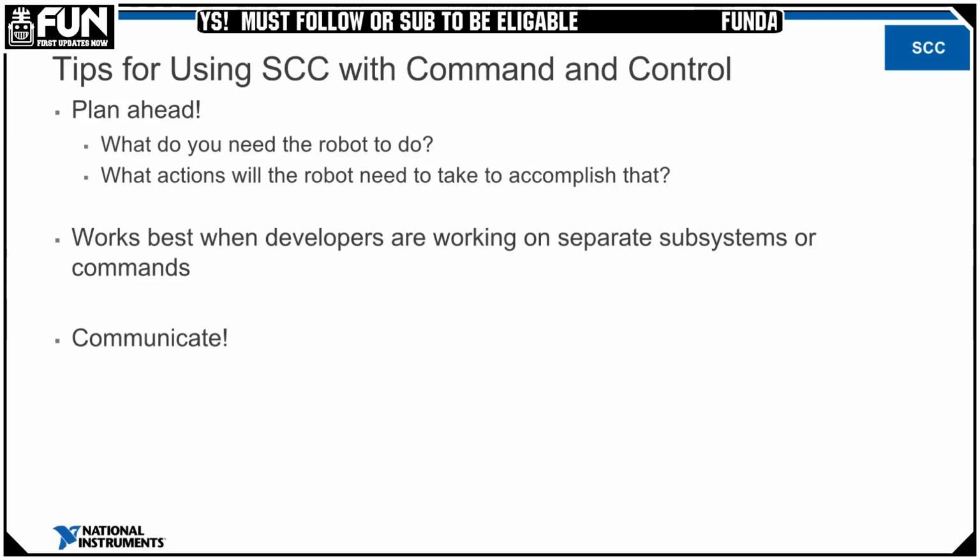Again, this does work best when developers are working on separate subsystems or separate commands, enforcing that modularity. Having two programmers working on the same VI on separate machines doesn't really work. You can't really copy and paste lines of code in. You can certainly copy and paste SubVIs in. That's a great idea. But either work in teams, work in pairs, or give everyone their own subsystem or command.